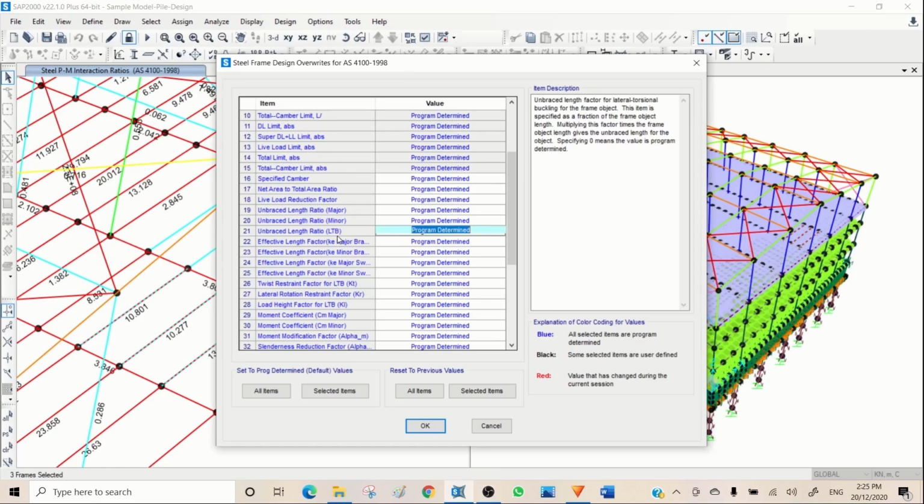So the question is, what is the proper reduction factor when we have a slab continuously connected to the beam? The answer is close to 0, because the compressive flange, which is the top flange of the beam in a single span beam, is the key part of the beam to determine the bending capacity.